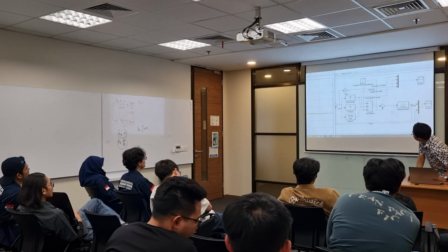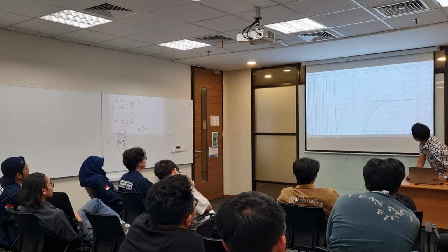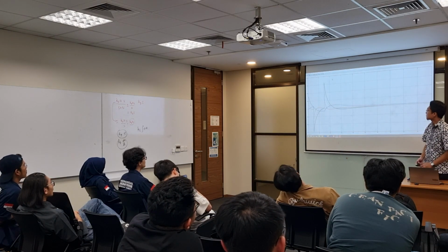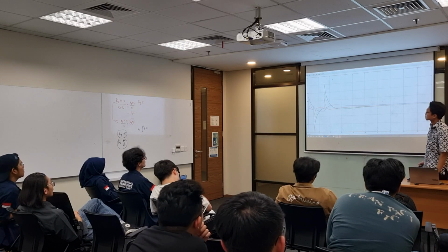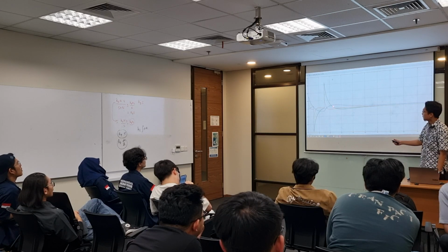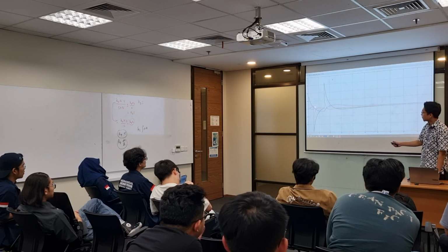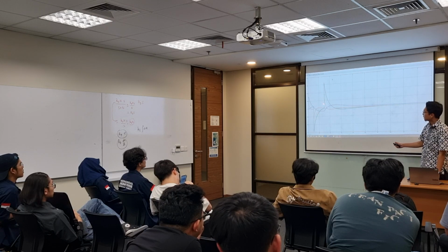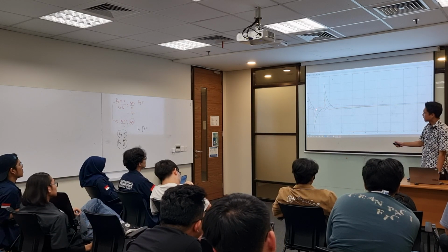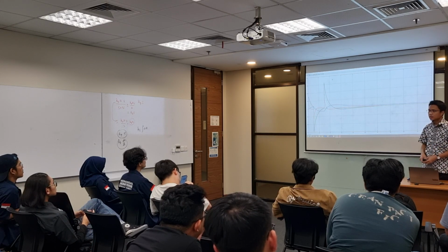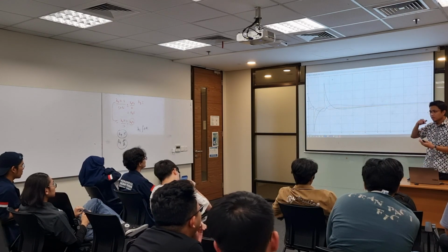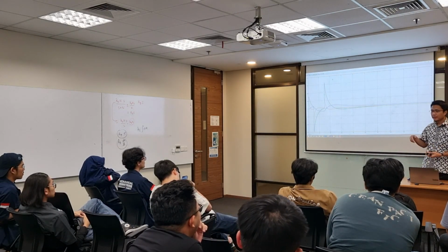And you see what happened with the control action. This is what happened with the control action. As you can see, the integral control is still very slow, and the derivative part helps when there is a big change in the desired value. When you change your desired value, the error changes.